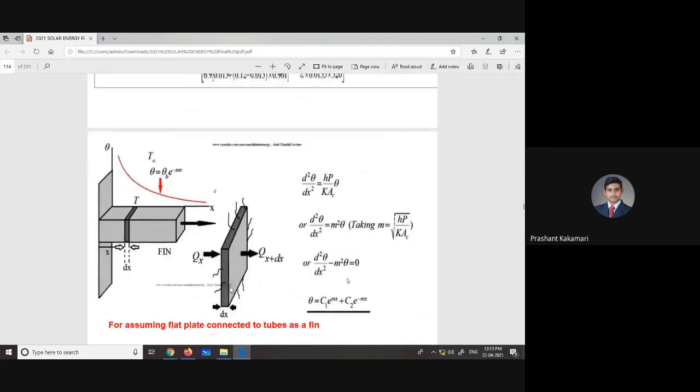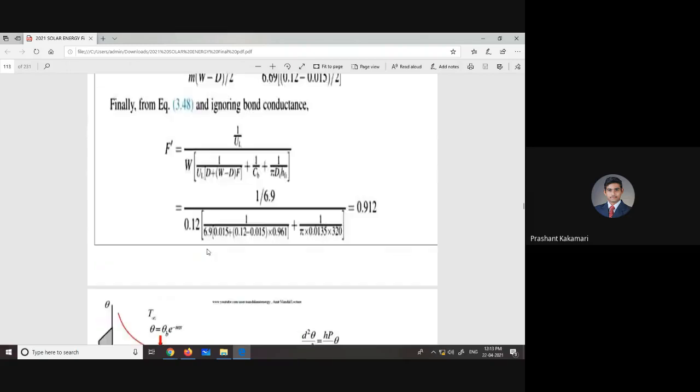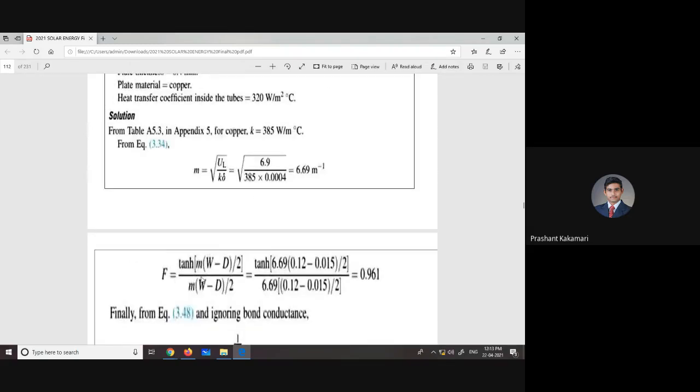wall. Here you can see this is at this surface, at the vertical wall. If you see, the temperature will be very high. Heat transfer is possible maximum, or the maximum possible heat transfer from this area, that you can consider. Then actual heat transfer taking place by the pin fin. So if you take that ratio, I can call it as the efficiency of the pin fin.